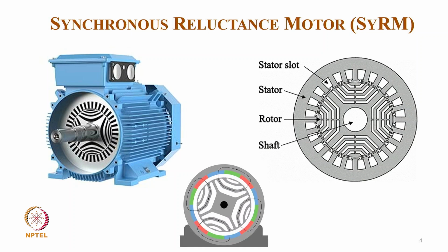So, you can think about the latest trend of the synchronous reluctance motor, how it looks. You can see the photograph as well as the cutaway, and from the animation you can see how it really rotates when you excite the three-phase winding of the stator by three-phase currents. Here we have a very interesting arrangement: a stator with a winding similar to an induction or typical permanent magnet synchronous motor.